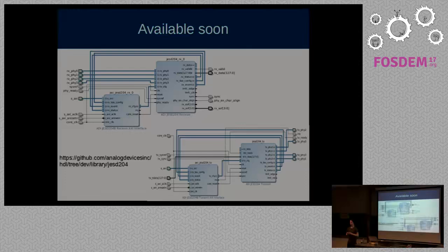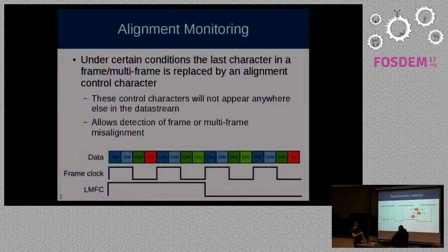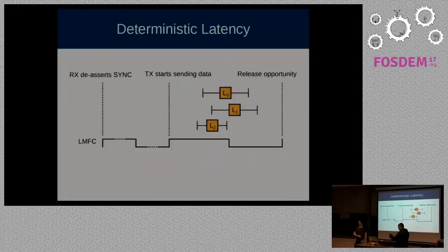I think that's one more question, if you have a short one. So, is the fixed latency mode mandatory in the standard, or is there also an option for best effort mode or something like that? So the question is if the latency is mandatory in the standard, and the answer is no. I mentioned this quickly in the beginning. There are 3 different subclasses. Subclass 0 basically just says, instead of having this release opportunity, just release the data when the last lane arrives. Okay, that's it. Thank you very much.